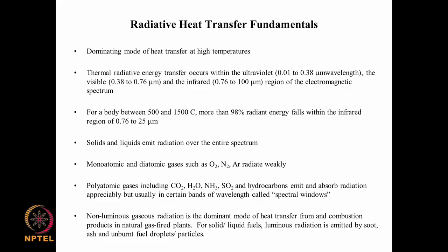We need to identify the domain, we need to identify the extra energy equation, and bring out essentially the specific heat and thermal conductivity of the fluid as special properties that need to be specified, and we also need to specify the thermal boundary condition at the surfaces which are bounding this flow domain, okay, computational domain.